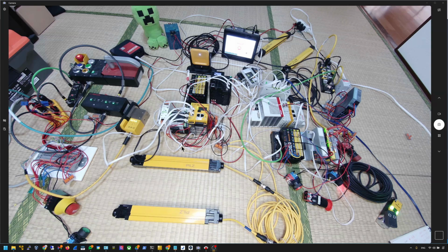And in the middle, we use a CODESYS controller connected with a Pilz FSoE master, and we communicate with the Weidmuller FSoE slave. And here is the free slot, the yellow slot, a Weidmuller FSoE slave. But we are also connecting to a normal EtherCAT slave, the non-safety slave, from Keyence, and also a safety light curtain from Pilz, which is also an FSoE slave. I also connect some local I/O to test the safety, and here is the light curtain guard from Pilz also.